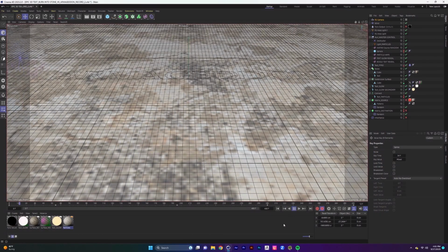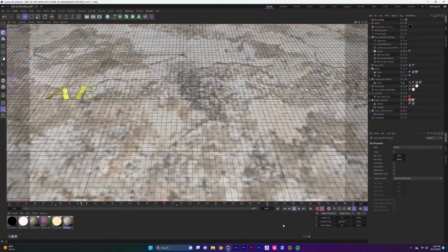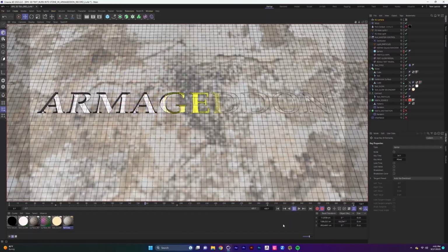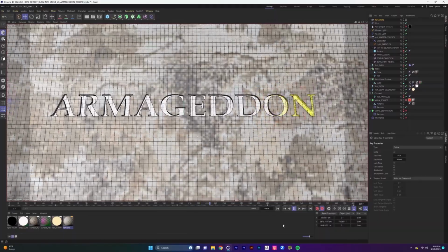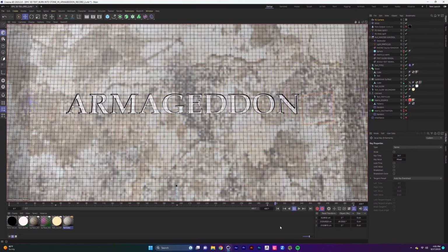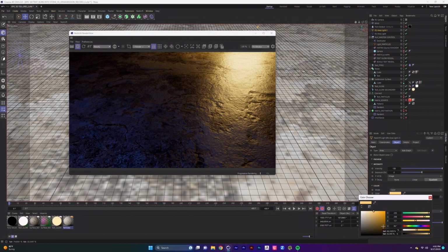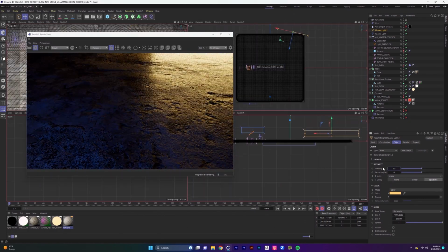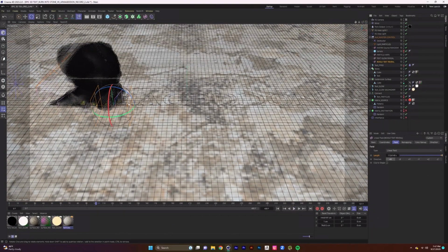And the way we built this scene, the master null fully reveals the text at frame 300, and from 300 to frame 400, the camera settles into an overhead position as the text glows and smolders and the smoke calms down so the text is actually legible. Now I'm going to adjust the lights a little bit just to fill out more of the space by widening them out. And you can adjust the lighting in your scene however you like.